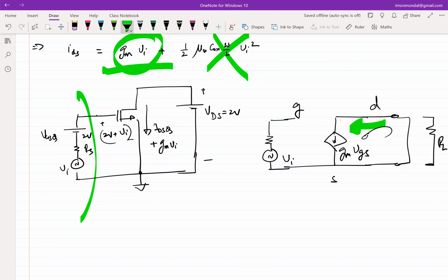So the next question is, how do I arrange that? I have an RL. How do I plug it into my total MOSFET circuit to develop that? In series with the battery, right? Just to ensure that everybody is on the same page, what happens if I connect it like this? It becomes shorted again, right? The voltage across RL is again clamped to 2 volts, right? So great, I can apply this in series with the battery.